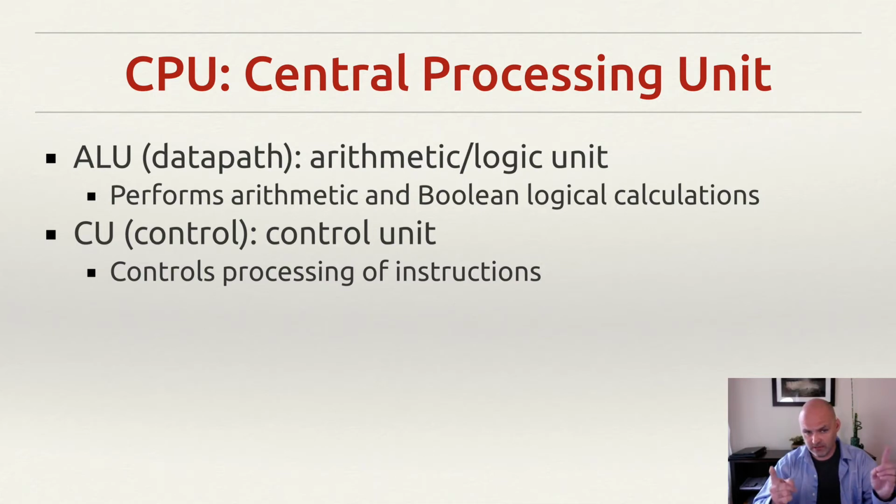So the control unit takes that 1010 instruction and turns on 2 out of 4 wires that are wired to the ALU. And when those 2 wires are wired on hot, that means that the ALU will do addition. Perhaps if we gave it 1011, that would mean that the ALU would do subtraction. It is the control unit's job to take that instruction and convert it to physical action of the hardware by actually changing the control wires of the hardware so that those things happen.